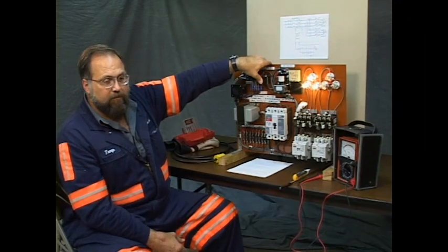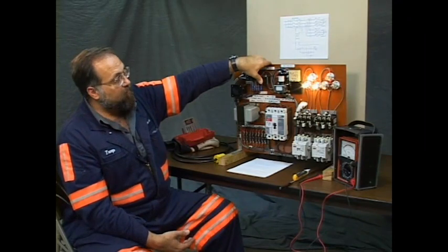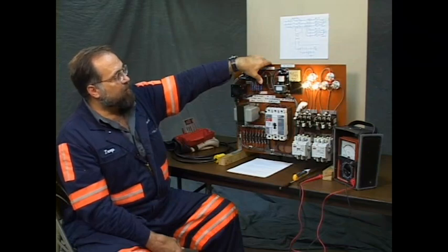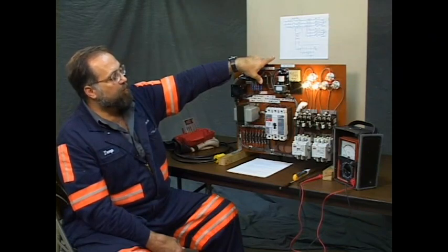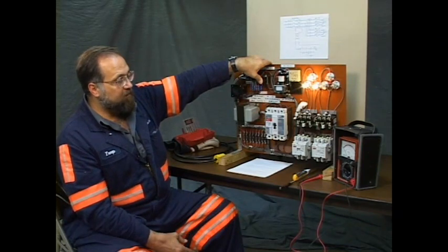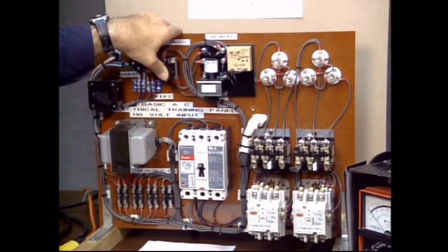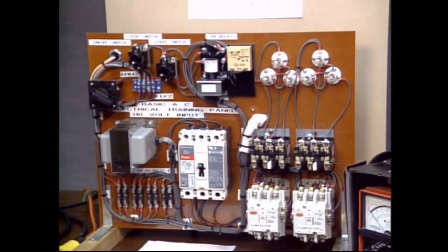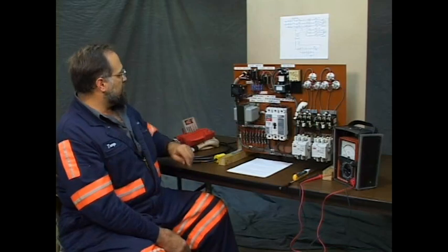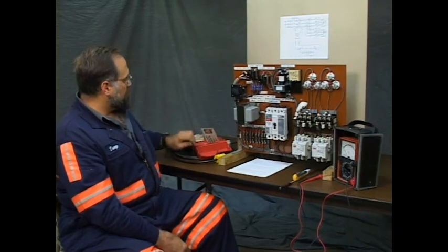It also said that when you release the start switch, you have no holding circuit. That's really not a surprise. The holding circuit's dependent upon both contactors going. Only A's gone. It's as reported, no holding circuit. Let's lock this thing out. Take the power off.